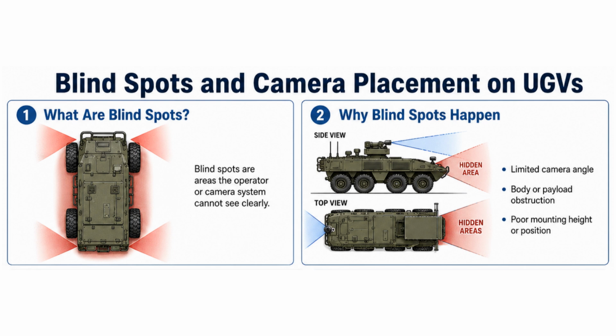The views should overlap, especially near the vehicle corners, so that gaps between cameras are minimized. Cameras should also be tilted slightly downward, kept clear of obstructions, and positioned where they can be protected and cleaned easily. Good placement improves safety and teleoperation.